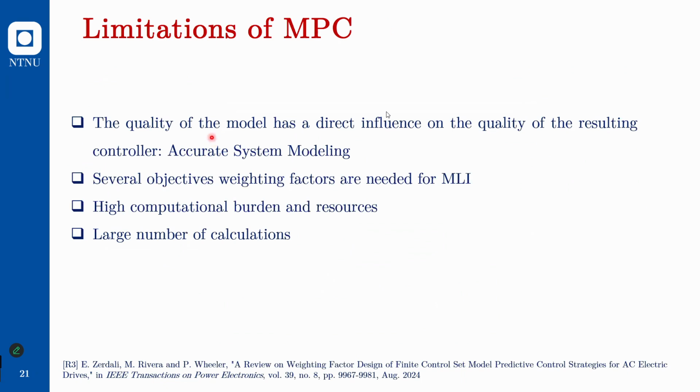So that is one of the limitations of the MPC. The other one is that it is very computationally heavy, because it is kind of an optimization algorithm. It solves a certain set of system models at every sampling instance. So these are the two limitations that we can possibly handle in different ways. But one suitable choice is to go for the neural network,